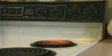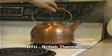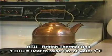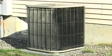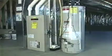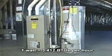Another common measurement of energy is the BTU, or British Thermal Unit. 1 BTU is the amount of heat necessary to raise 1 pound of water 1 degree Fahrenheit. The BTU is often used to measure the cooling capacity of air conditioning equipment, or the heating capacity of a heating system. 1 watt is equal to 3.412 BTUs per hour.